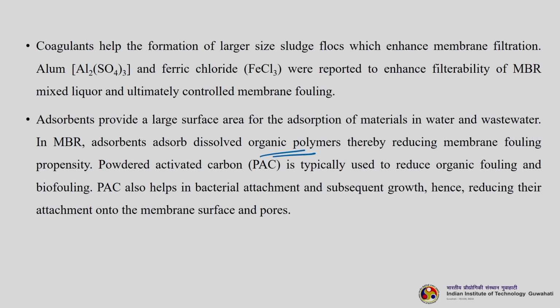Powdered activated carbon can be used because its surface area is far higher than that of granular activated carbon, to reduce organic fouling and biofouling, but the problem with powdered activated carbon is to get rid of it or filter it, basically take it out. So, many times you use granular activated carbon, which is known as GAC.